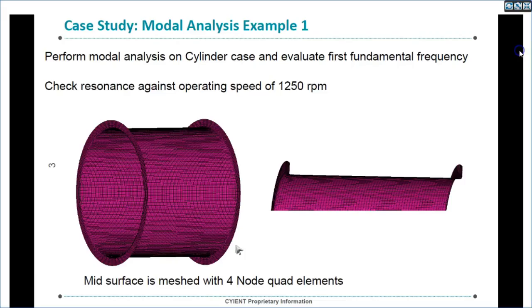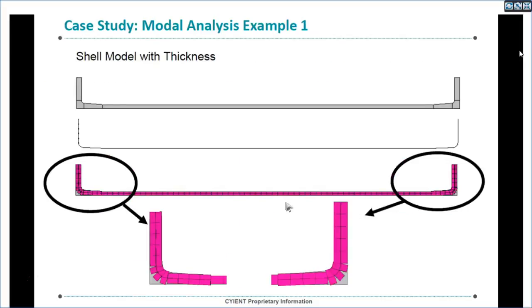So the case study is to perform modal analysis on this case and check the resonance. Okay. What we have taken is a shell model instead of building a 3D model. We have used shell elements to build the FE model. We have meshed with the shell elements and assigned real constants. You see here, these are the real constants assignment.